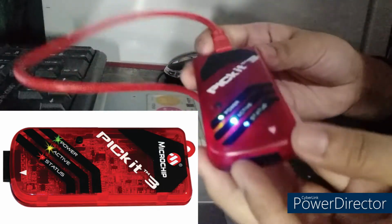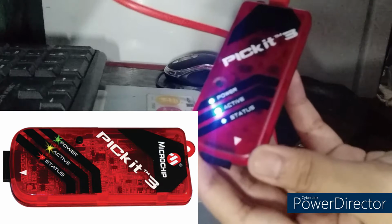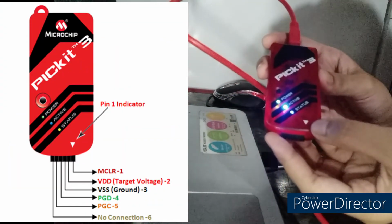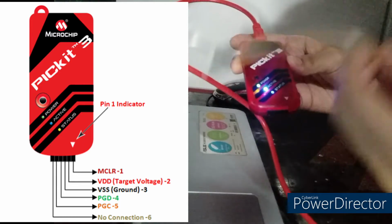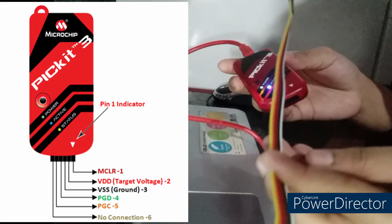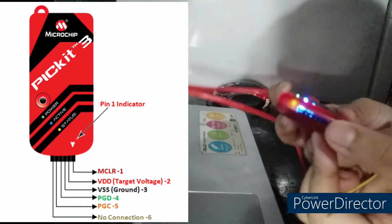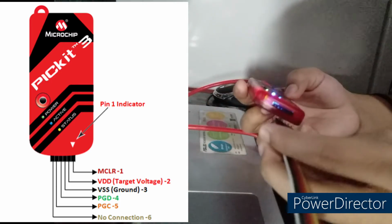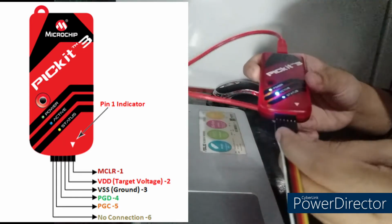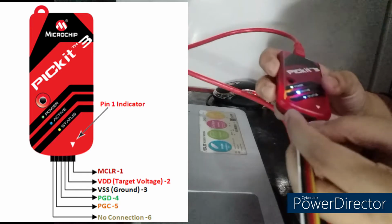So that's the part of our PICkit 3. Here on our PICkit 3, we have an arrow. That's our pin 1 indicator. Since with my PICkit 3 I already have this joint wire, which will be connected to this black part of our PICkit 3, I will set the yellow wire as my connection to pin number 1 of my IC later on, and the pin number 1 of my PICkit 3.